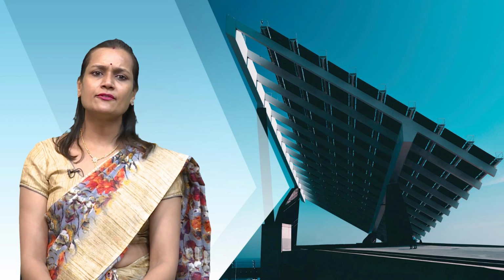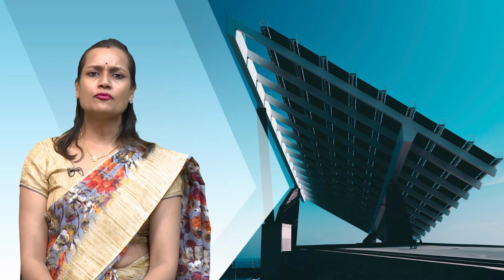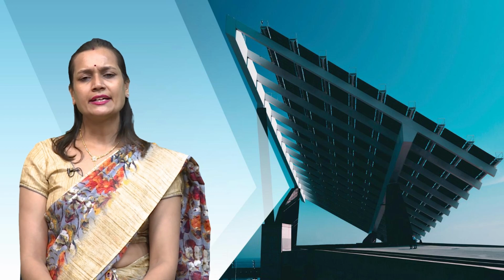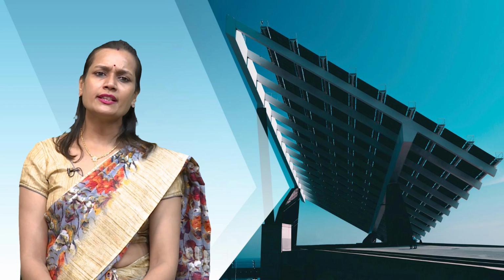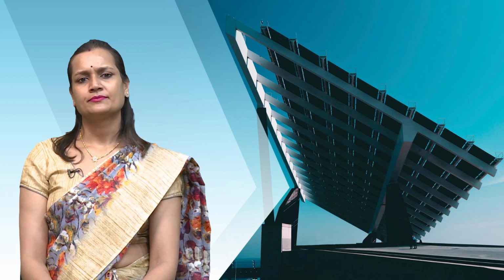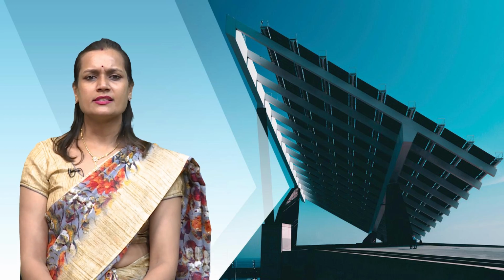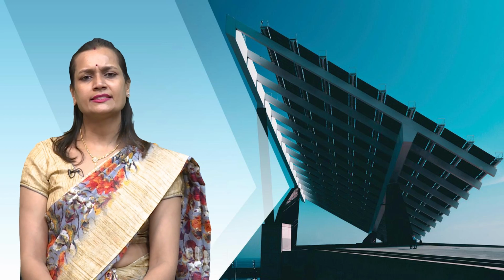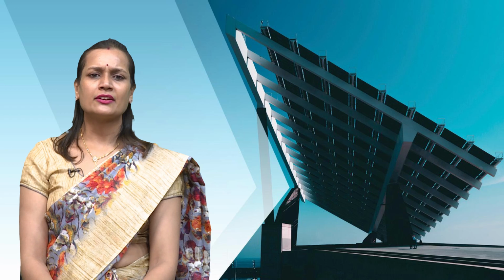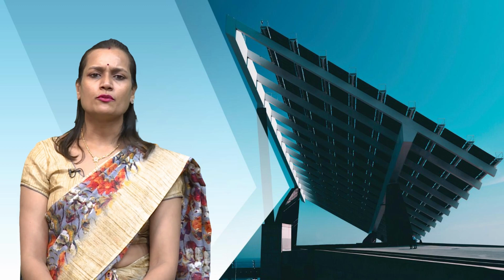It transfers the heat from the heat transfer fluid to the water inside the storage tank, thus raising the temperature of the water. The heated water is stored in the tank until it is needed. When hot water is required for showers or other purposes, it is drawn from the storage tank. If the water in the tank is not hot enough, a backup heating source, for example an electric or gas element, may be used to ensure a continuous supply of hot water.